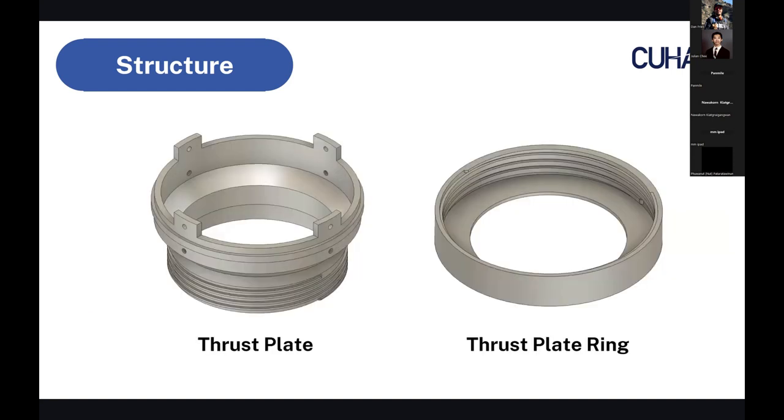Now I'm going to talk about the thrust plate design. Today we decided to merge the flange retainer and the thrust plate into one piece. The reason is that the addition of the boat tail required that the motor be a bit lower than usual, so the old flange retainer would not work. If you can see, there are 2 rows of M4 bolts. The upper one connects the thrust plate to the airframe, and the lower row connects with the boat tail. The thrust plate retaining ring and the thrust plate all use a custom thread.